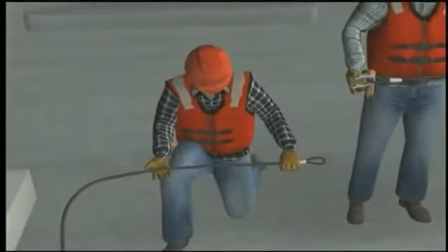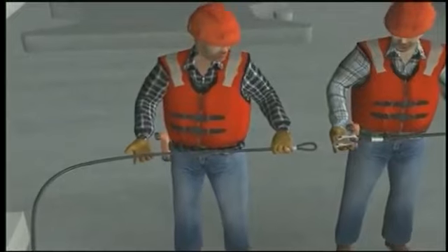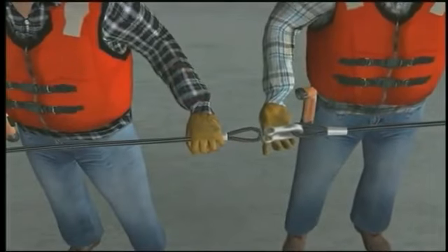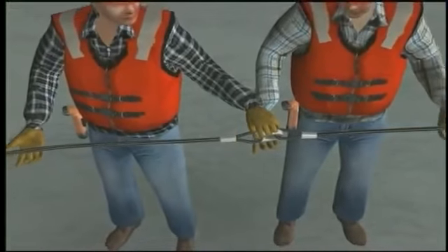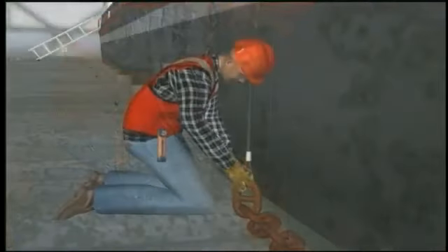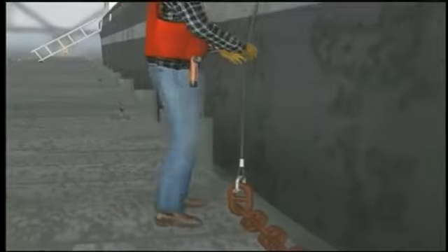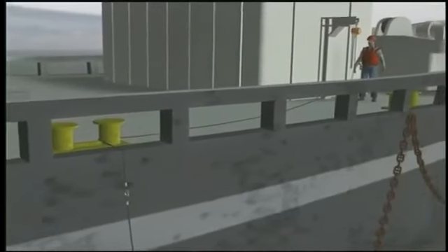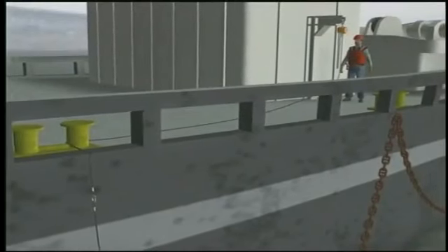The men began by attaching several short wire rope slings end to end with shackles, creating a longer hoisting line. One end of the sling assembly was attached to the unlinked end of the mooring chain. The other end of the sling assembly was led through a bit on the deck edge of the vessel and then attached to a chainfall.